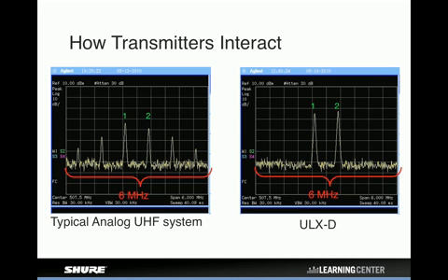But I think this illustrates, again, why you can't randomly select frequencies and just say, well, they're far enough apart. You could look at these two and say, well, these frequencies are 2 megahertz apart. That's great. I'll just space all of my frequencies 2 megahertz apart, and then they should be far enough apart. Except in that case, if you did that, every system you were using would be landing on intermod frequencies, and you'd be interfering with yourself in the worst possible case scenario.